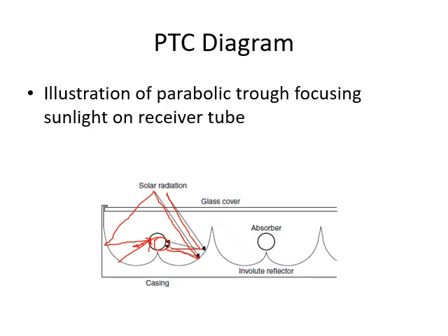Depending on the shape, they can also be called an involute reflector. On the top there may be a glass cover, with everything combined together. Adding the glass cover increases the greenhouse effect inside, aiding in the increase in temperature of the working fluid, or heat transfer fluid, inside the absorber.